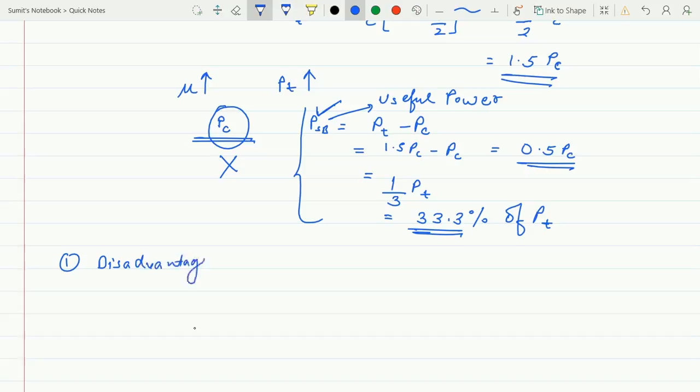So the first disadvantage of AM we saw was that the bandwidth becomes twice. Always we want to keep the bandwidth as minimum, because in communication we are transmitting through a wireless system. The bandwidth is the most costly part. So optimizing the bandwidth, keeping it to the minimum possible, is what we want to design our system for, so that it takes minimum bandwidth.